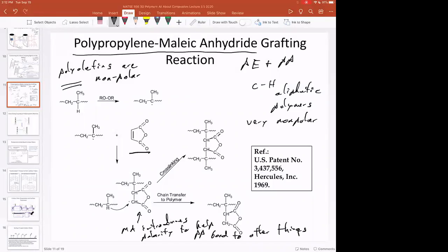like fillers. So if you try and make a polypropylene composite out of just pure polypropylene, it's really hard to get anything to mix in there. And so that's why when you go to ExxonMobil and say, I'm going to make a polypropylene composite, but I need 5% maleic anhydride in polypropylene, they sell that polymer specifically to make polypropylene composites and get this good dispersion or get these interactions between the polymer chain and the filler.